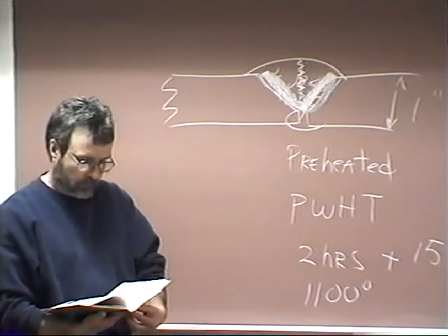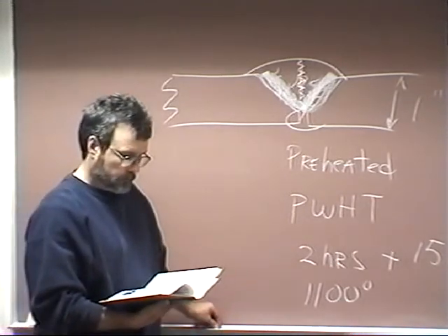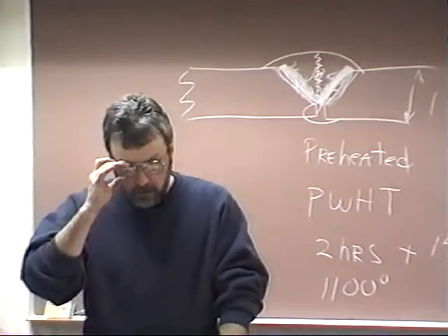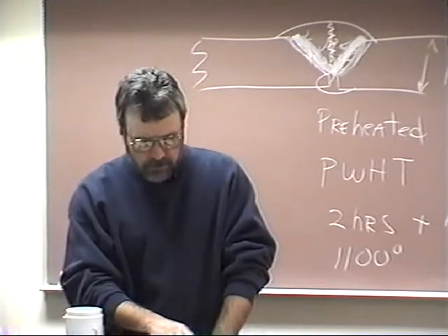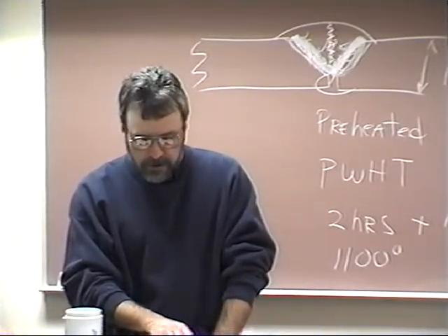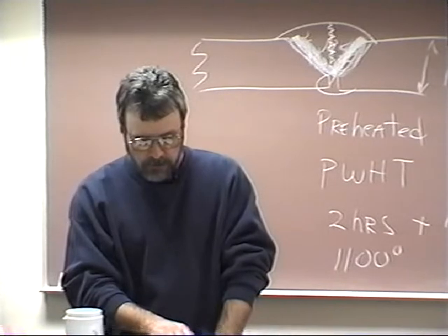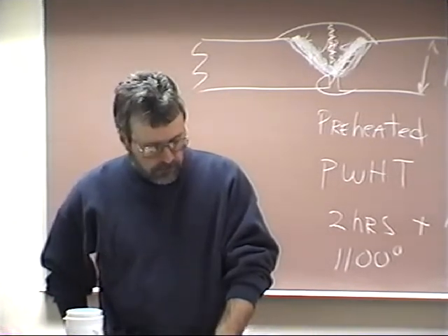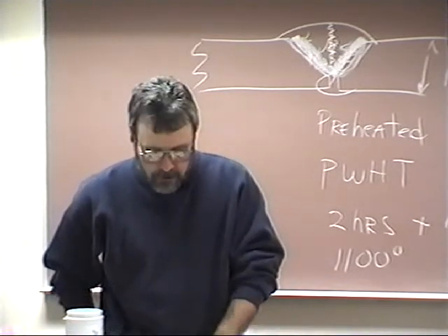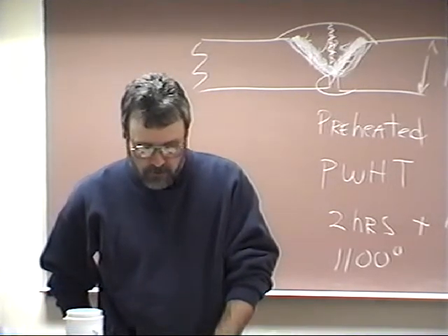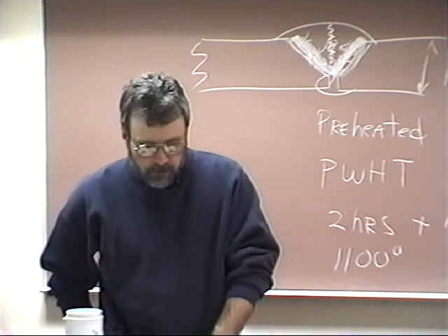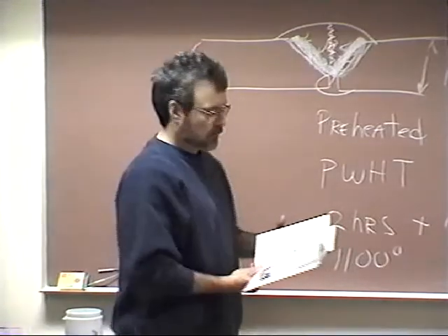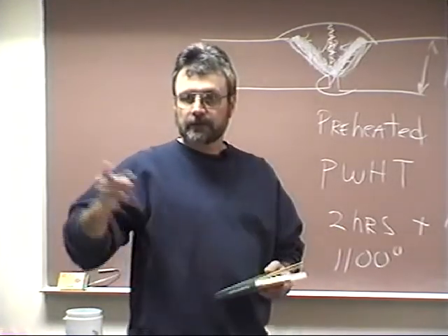So on page 211 in your text, it says, a thick weld having a larger volume of metal will accommodate more deformation without cracking than will a thin weld. Therefore, as shown in figure 12E, which is part of the figure on page 210, a heavy weld is less likely to crack than a small weld when they are on thick metal sections. Okay, that's two types of cracking. Now I want to go ahead and talk about undercutting.